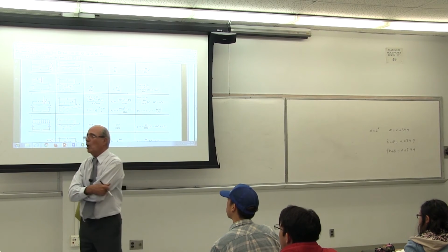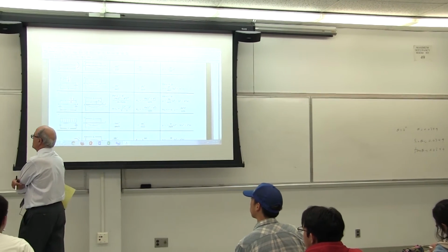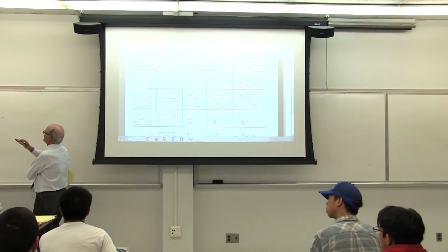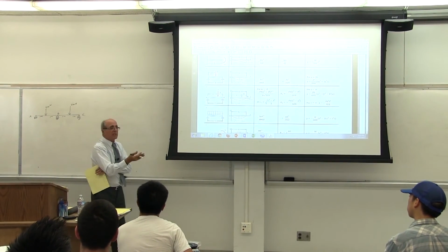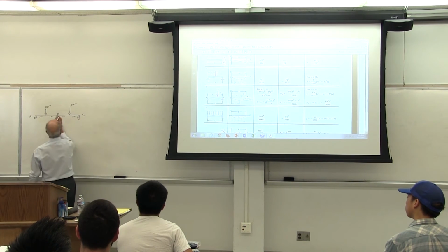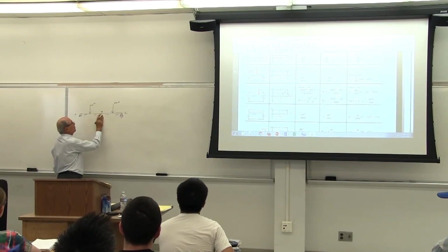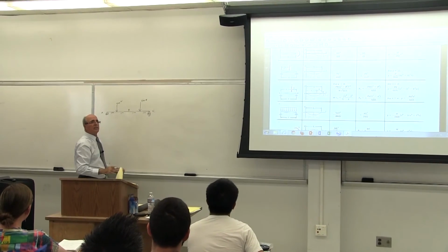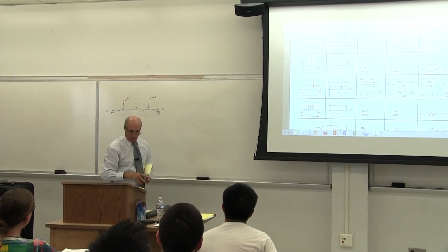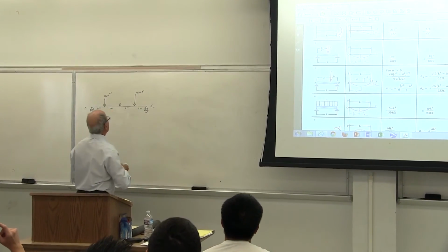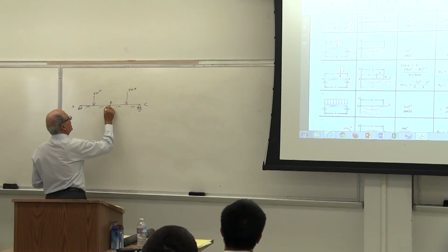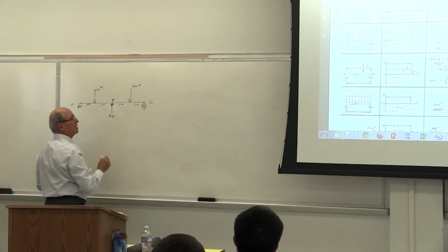Now, how do I show? I want to use the superposition method to find the reactions at A, B, and C. Do exactly what? Is this a support there? Yes or no? If I take this support out, what should I put underneath it? I should put there a reaction. But do I know the magnitude of that one? No. So I'm going to put RB there.